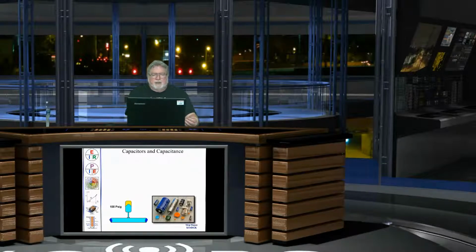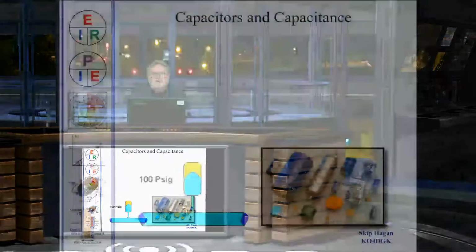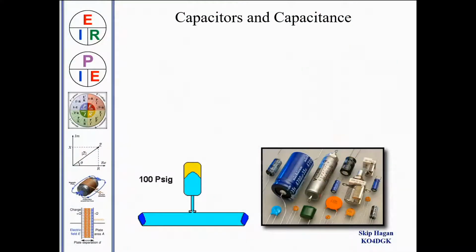So when you use the water, you're going to have a pressure drop, and that accumulator, because of the pressure charge on it, is going to continue and hold that water pressure for a few seconds so that you actually get a usable stream of water. And that's an accumulator. And notice the accumulator doesn't produce any water. It just accepts a charge of water and discharges that water when the pressure in the system goes down.